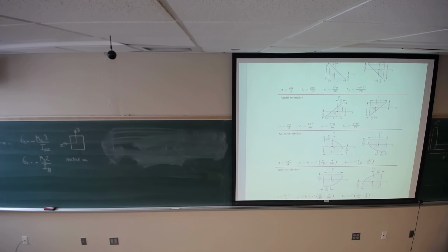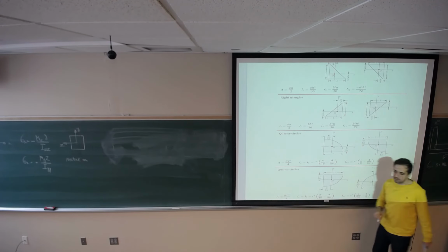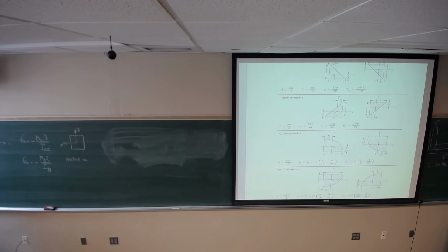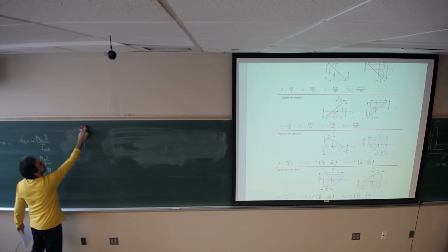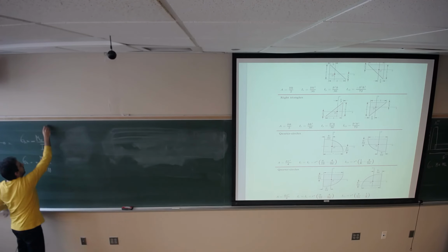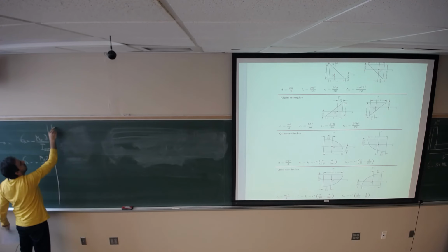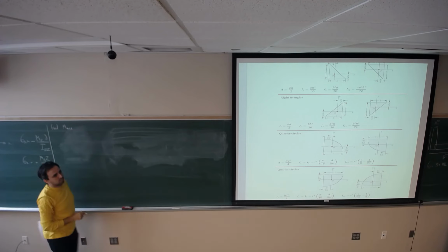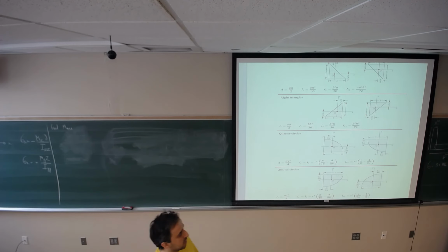We need that this beam is made of a material which can support normal stress maximum equals to 150 megapascal. So if the stress applied to this cross section exceeds 150 MPa, it's gonna fail. So we would like to know what would be the maximum bending moment, M max, that we can apply to the cross section?